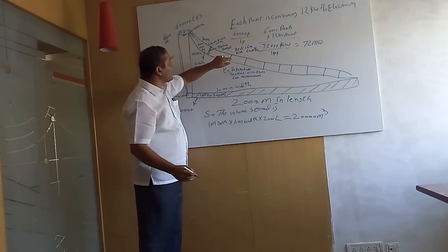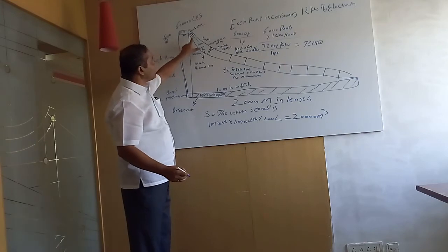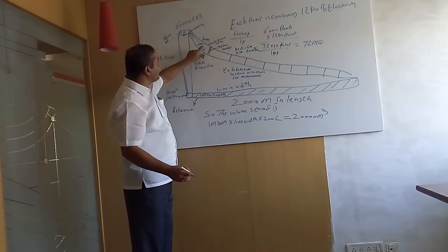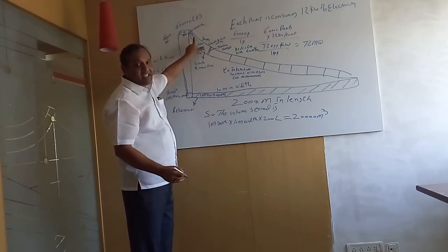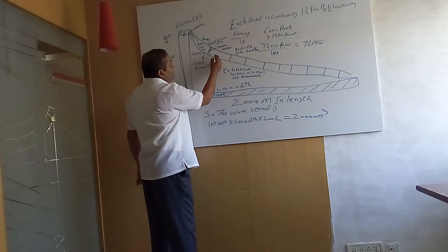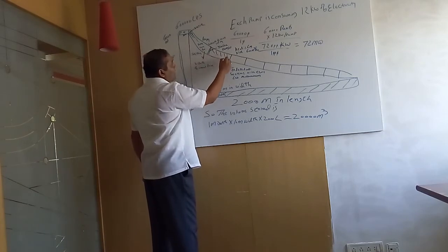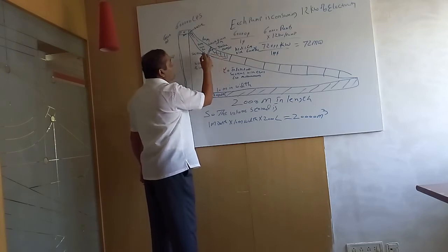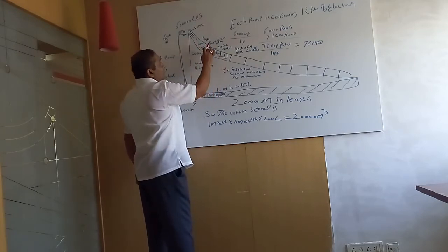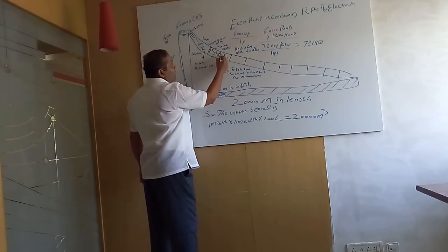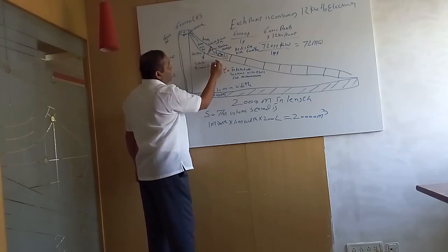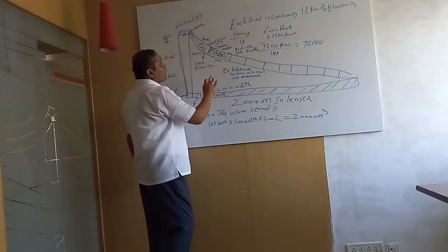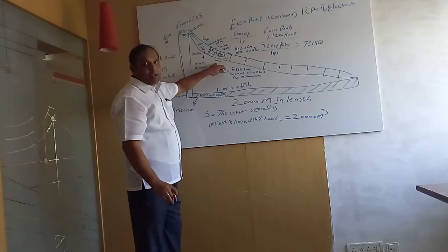So in this one particular sector, 600 meter cube per second is coming down, and for 10 seconds the turbine will rotate. So as soon as the 10 seconds are completed, this one particular section is completely empty. Then again coming to this particular sector, it is completely filled with water. This sector also is identical to the above sector. So here also the depth is 6 meters, the length is 100 meters, the width is 10 meters. So here also 6000 meter cube volume is there.